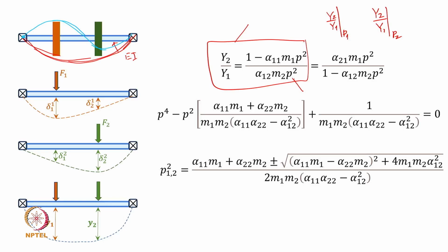So, the second mode will be this kind of a second mode, where when this disc is moving upwards, this disc is going to move downwards, and so on, right. So, then your y2 by y1 will be negative basically. It is quite similar to x2 upon x1 that we discussed for a 2 mass case with specific stiffness values. This turned out to be +1, and then in the next mode, second mode, this turned out to be -1. You remember that? So, the masses were moving in the opposite phase.